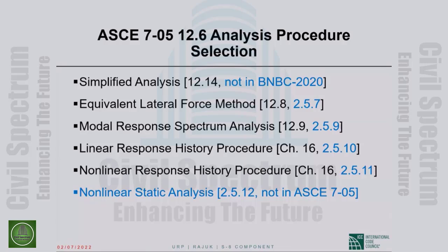Equivalent lateral force procedure was allowed to be used under restrictions, as you will see very clearly in BNBC 2020, and I'll point those out. But in the latest US codes, in ASCE 7-22, the electronic version has been released. Paper copies are still not available. It will be sometime this month. Be that as it may, in this document, equivalent lateral force procedure will be allowed for basically everything.